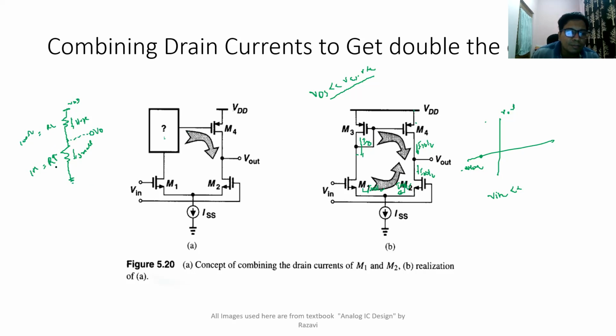If below VDD there is a resistance of 1 mega, and above it a very small resistance. So this is very large, this is very small, so you can assume that complete VDD is going to appear here. Is it or not? Yes, sir. There is going to be very little drop here, and the same complete VDD is going to appear here. Am I right or wrong? Yes, sir. So V naught will be equal to VDD. In this case, V naught will be equal to VDD.